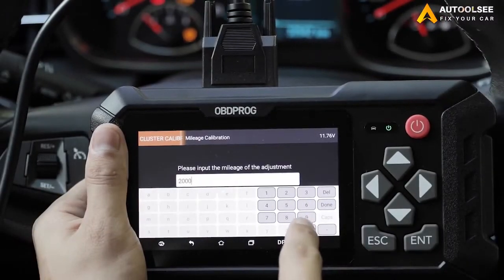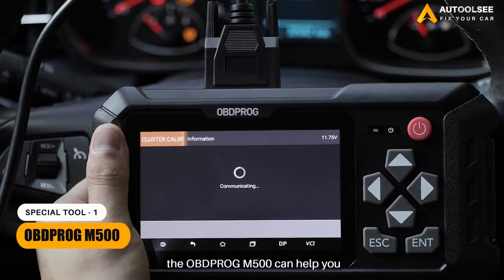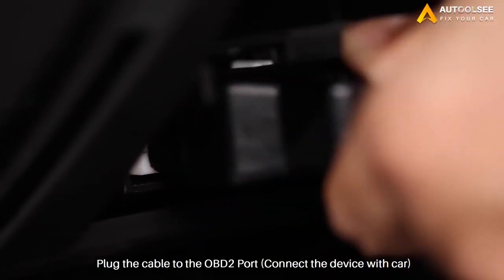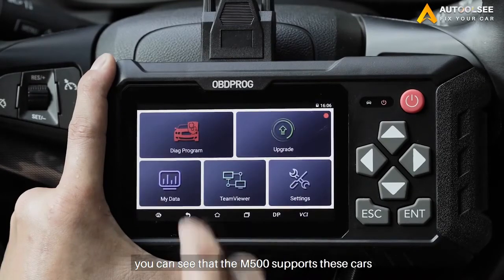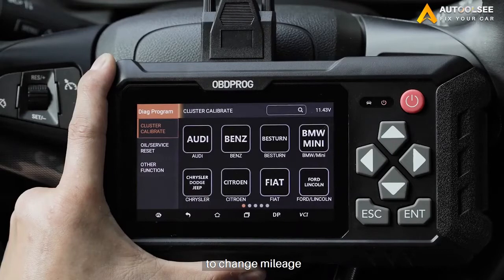Okay, last tool. Sometimes if you change the cluster and you need to adjust the mileage, the M500 can help you. Plug the cable to the OBD2 port. Click Guide Program. You can see that the M500 supports these cars to change mileage. And this device is standard.